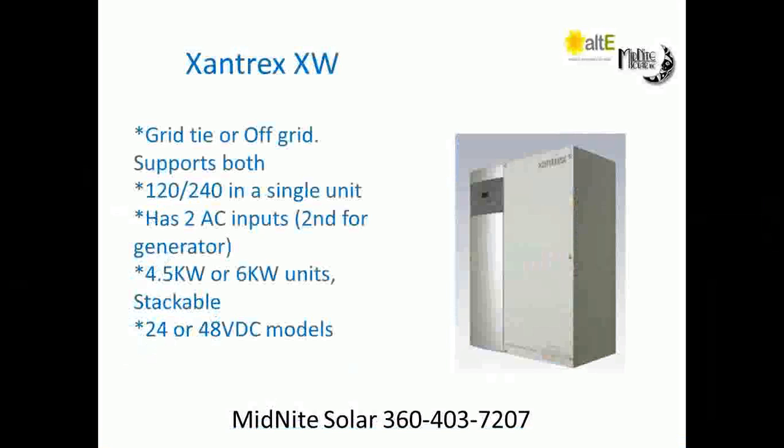SMA does generator support, and what generator support is, let's say you've got a 5 kW generator, you live off grid, and you got a 6 kW Xantrex XW, and you've got a 7 or 8 kW motor load that you want to start, or whatever the load may be, and you only do it rarely, so you really don't want to buy the second inverter just to start that load. You go fire up your generator, and then you start the load, and the two will combine together to make an 11 kW power system at that point and start your load.